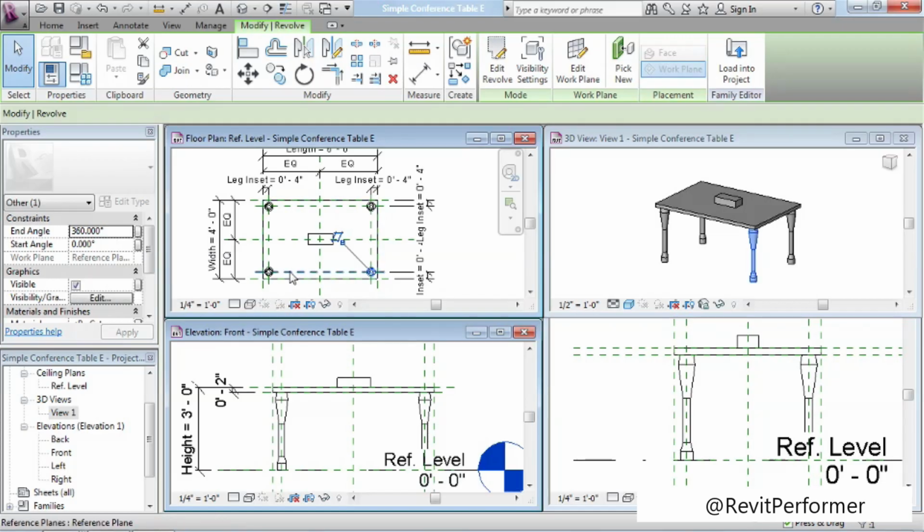Now let's compare that to one of the legs on the left-hand side. I could select either one. I'm going to see that that little icon is not there. There's no disassociate icon. And the reason there's no disassociate icon is because the work plane is already non-associated. When we mirrored to the other side, it lost its association to the work plane.